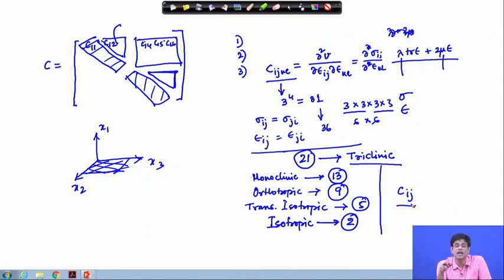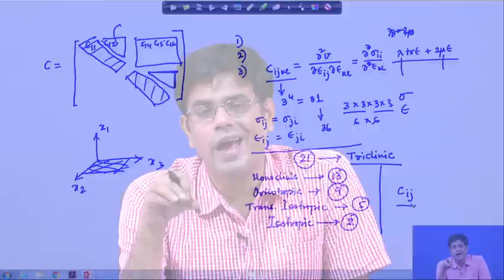which is, the modulus of nu ij, if you remember, is less than or equal to square root of Ei by Ej. Those things we have derived. So, this poses some restriction on the engineering constants, which cannot be arbitrary. Then we derived the rotated constants: if the structural axis and the material axis are not aligned, how the constitutive matrix will look like, that we have also derived.